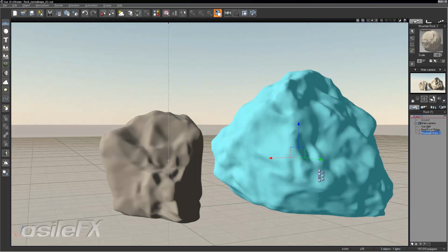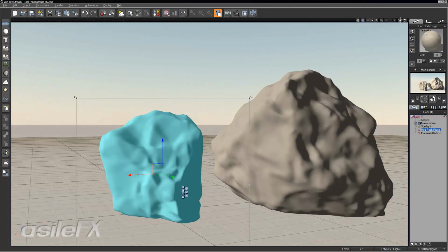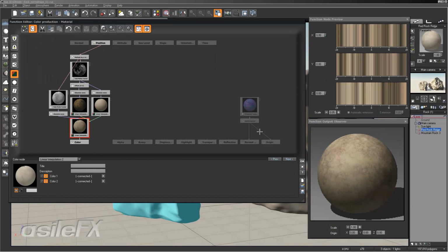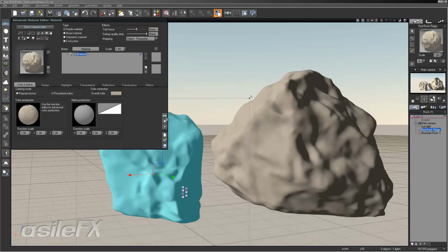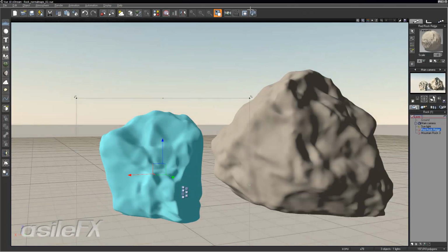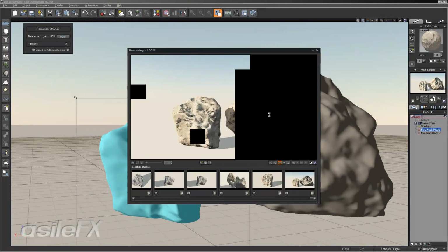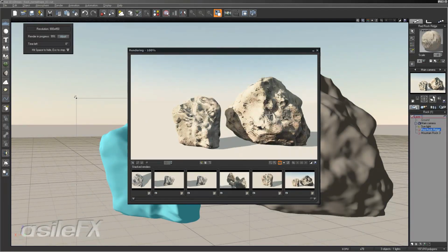And then we'll also have to go back to the other object that we brought it from, in this case, and reconnect those. So this is really the only way to apply the normal map in that fashion, if we were to save the normal map out, or save the material with the normal map out, and try to apply it to any other object.